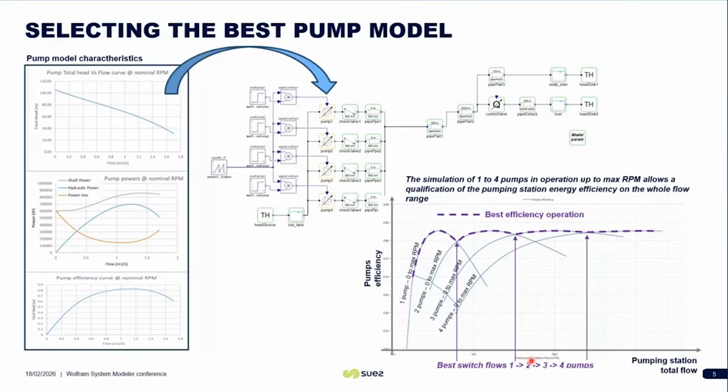Okay, so now we have a pipe network with diameters. So we know the total head we need on the pumps, well, the discharge pressure, because we have the networks, and we typically receive several offers from pump manufacturers, and we have to select a pump model. The manufacturers typically send us this type of curves.